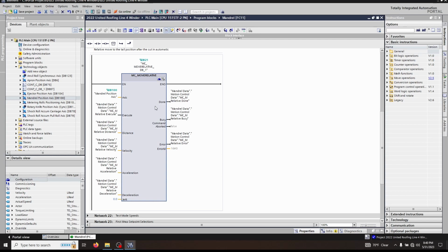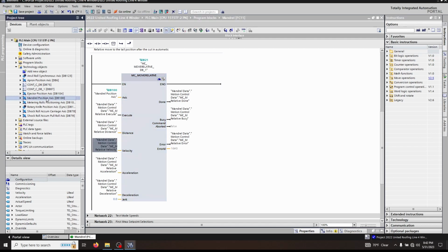First, if this velocity is 0 and you execute this move, the busy signal will go true and it will sit there forever, because the velocity is only moved into the block once when you trigger the execute. If you go in and change the velocity after the fact on this MoveRelative, it still will not move. You have to re-trigger the execute. But there is a way to change the velocity in the middle of the move by changing what is called the override velocity.